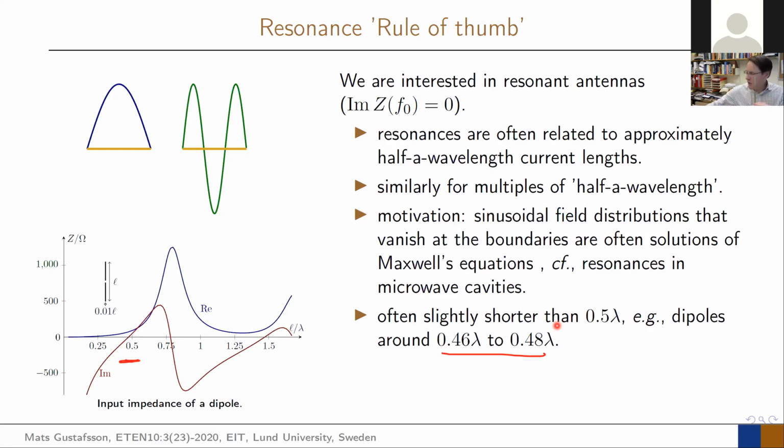What do you do? You take a pair of scissors, as a traditional antenna design. You can start cutting it. It means I can make it shorter, until the antenna becomes resonant. So I don't have to really calculate it in those cases. I just make it a little bit shorter. I measure it. Not correct. A little bit shorter. Not correct. A little bit shorter. Oh, resonant. And I'm happy. So the first start is very good with this half a wavelength. And it gives you the idea where you should be. And then you just make it slightly shorter.